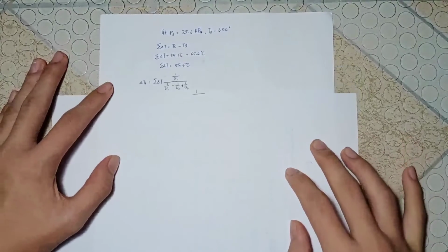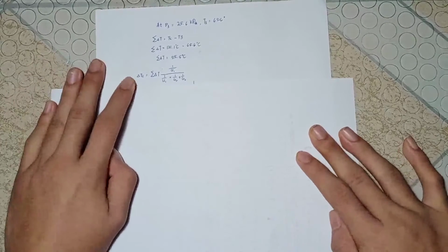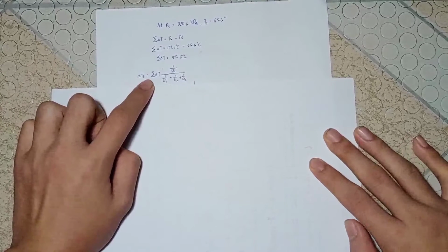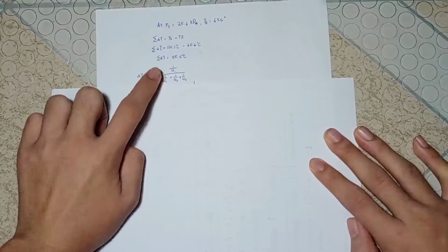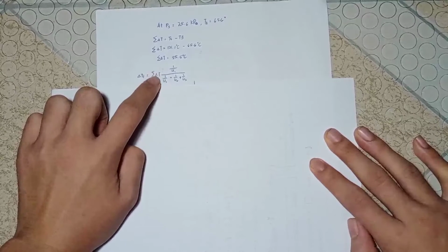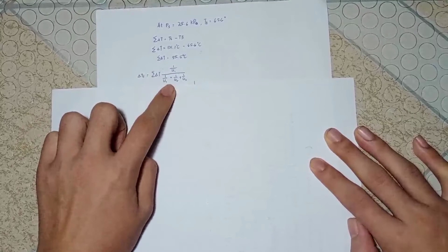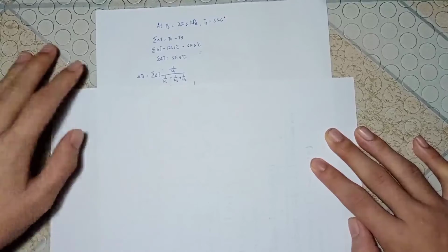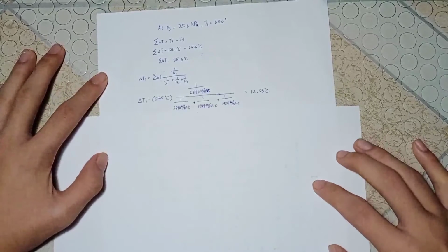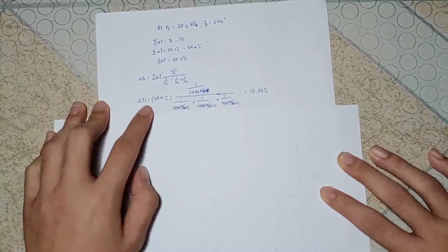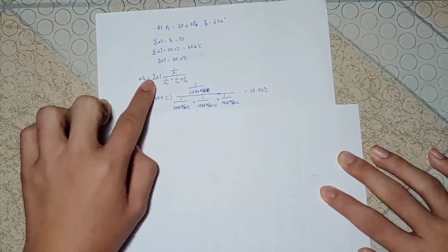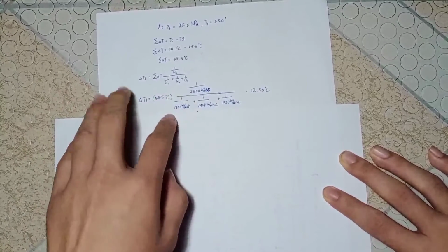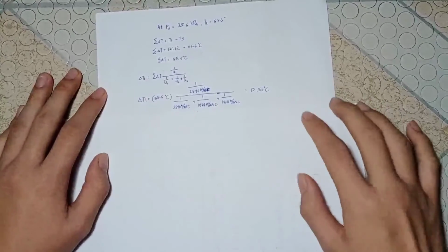Next thing to find is T1 and delta T1. The formula to use for delta T1 is the summation of delta T times 1 over heat coefficient 1, over 1 over heat coefficient 1 plus 1 over heat coefficient 2 plus 1 over heat coefficient 3. Sorry for that. So we just plug in the values, and the summation of delta T here was 55.5. The heat coefficients were already given, so we just plug in and find the answer.